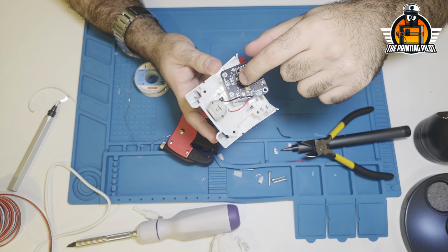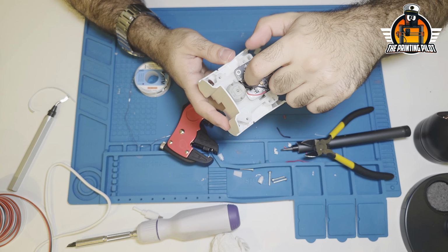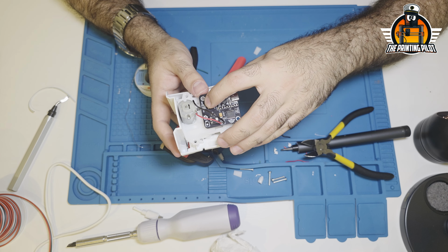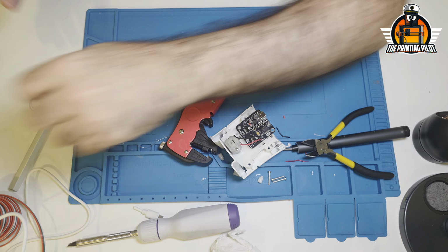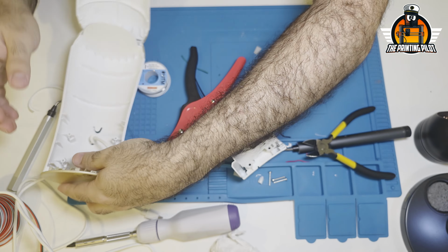And the last thing we're going to solder is the power, and over here the power orientation is important, the polarity I mean. So plus and minus is important, so make sure to solder ground to ground, VCC to VCC. And when you cut and expose your USB cable leads, you might have more than one cable there, because you might have a cable that also moves data.